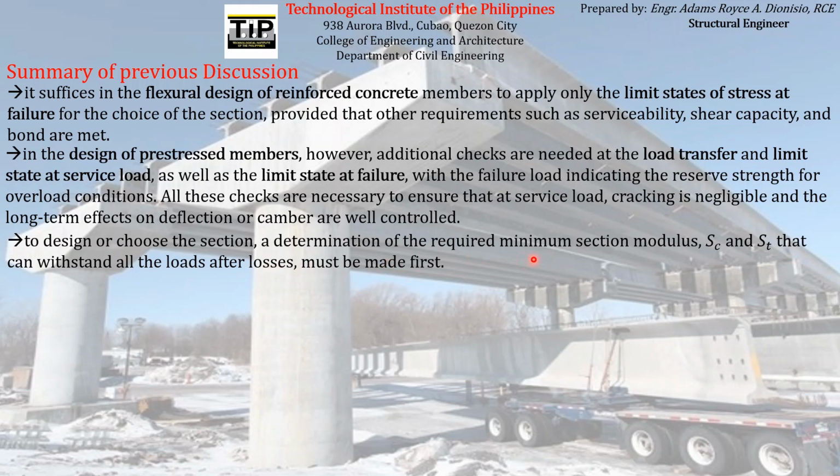So that is what we are doing when we conduct service load design. Although service load design is dependent also on the profile of the tendon that we are supposed to put on the pre-stressed concrete member that we are designing. So if there will be a different eccentricity or profile for our tendon or for our pre-stressing reinforcement, there will be a different formula for finding the minimum section modulus.